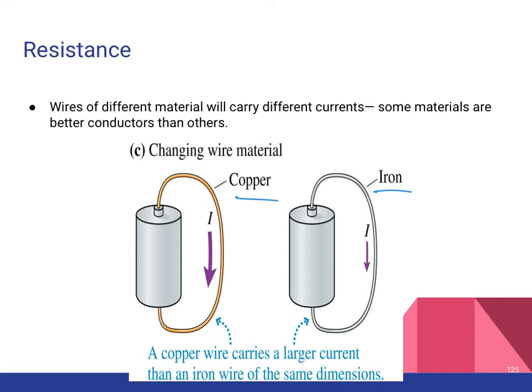In your house, a lot of times you have copper wire. Now, what's the problem with copper wire? Well, it's kind of expensive. So sometimes in your house, especially if you have a thick wire, like if you upgrade your house to 200 amp instead of 100 amp, you will have a much thicker wire. In order to save some money, they make those out of aluminum. Well, aluminum has other issues. It oxidizes, so electricians take special precautions to make sure it doesn't.